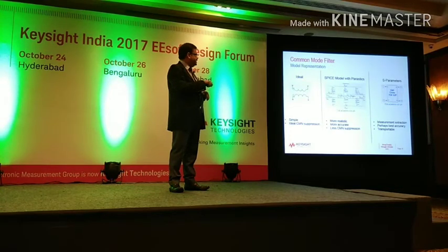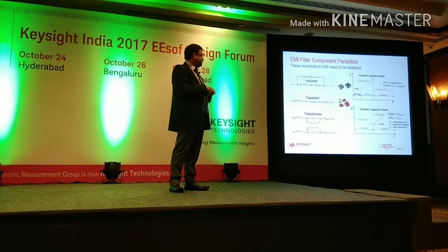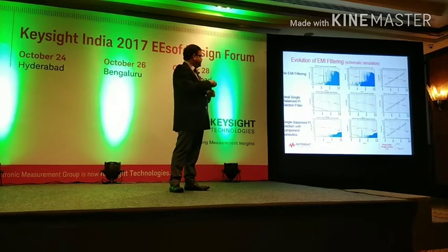Again, these can be with parasitics. You can have S-parameters. You can model all of those behaviors, all the parasitics. So with no EMI filtering, this is what we got. With a bi-section filter for rejecting the common mode noise, you can see everything is pretty smooth. So we are complying. So we went ahead and made the PCB layout.